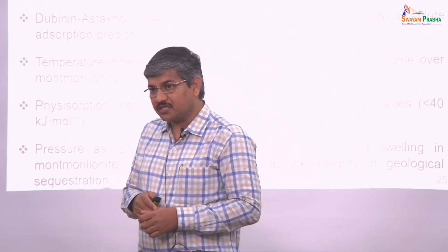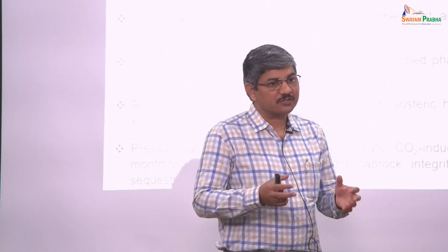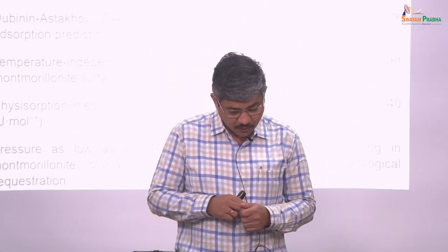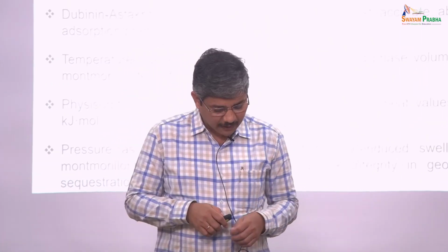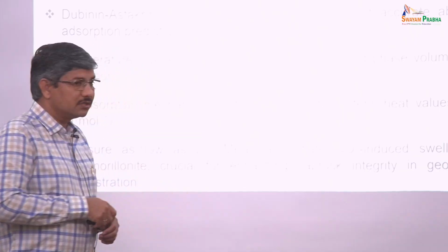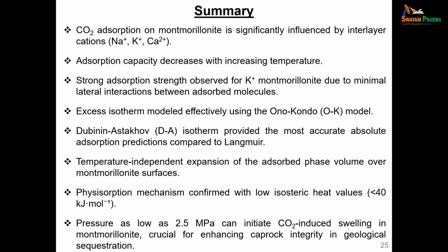Now, people ask me whether the clay will swell when you introduce a gas at atmospheric level. The answer is no. You need a minimum pressure of at least 2.5 megapascal to initiate the CO2-induced, adsorption-induced swelling, in the case of the montmorillonite we considered. So don't expect swelling of clays at atmospheric level. Otherwise, you may be thinking, what will happen to my building foundation because of the rise in CO2 concentration in the atmosphere. Nothing will happen to your building foundation. That much I can guarantee you, unless you really increase the pressure.